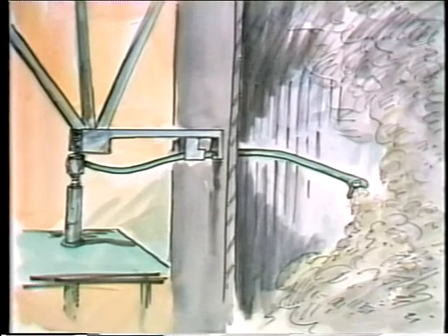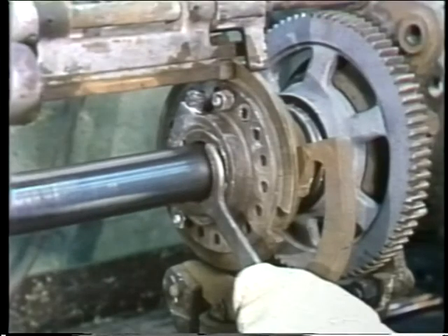If an element binds, it can cause rapid erosion of boiler tubes because the blowing medium is directed over a small area for a long time under extreme temperatures and pressures. Things that cause binding of the element include warping of feed tubes or elements, an accumulation of slag or ash where the element enters the boiler, over-tightening packing or not lubricating packing properly when it's installed.